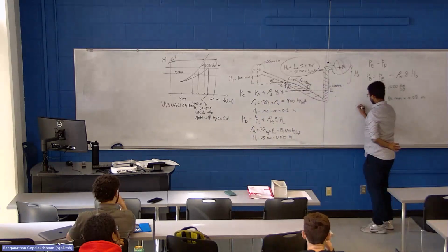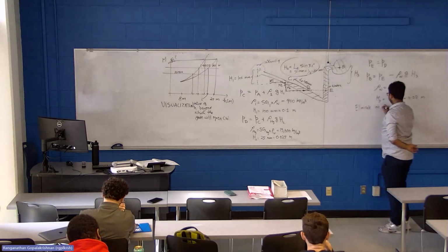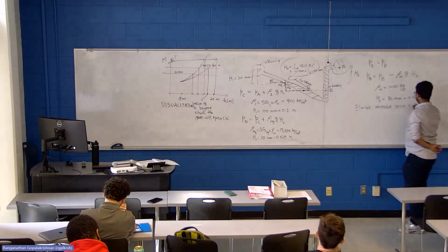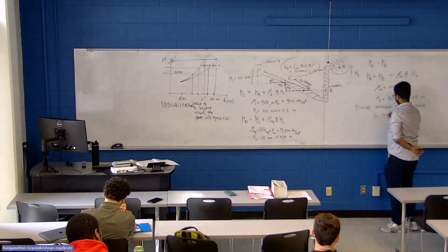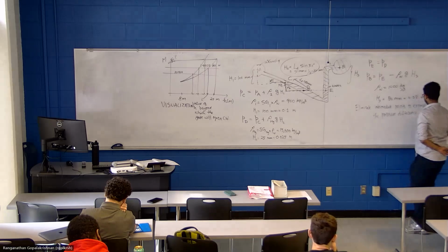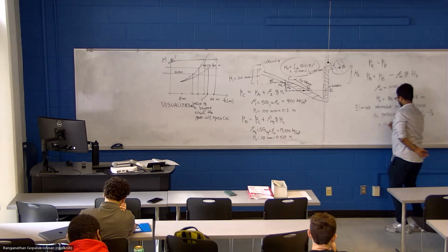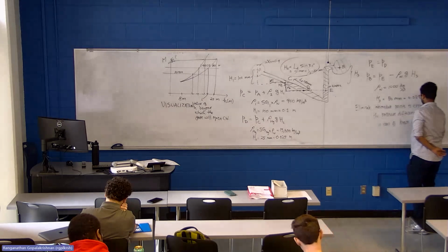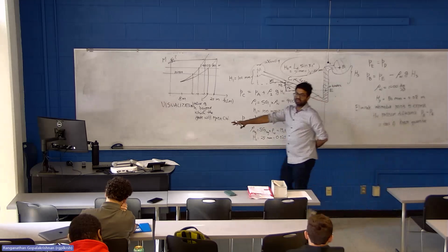You just have to eliminate intermediate points to express the pressure difference PA minus PB in terms of known quantities. That's what calculating means, right? If you write PA minus PB equal to everything else, you compute that.